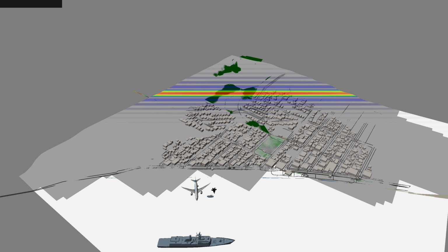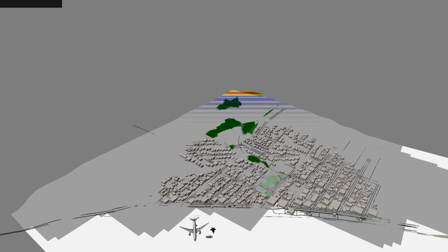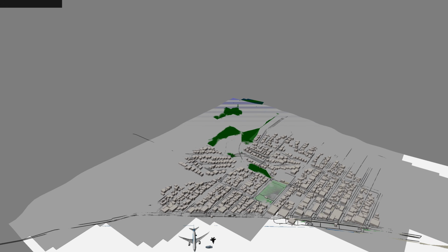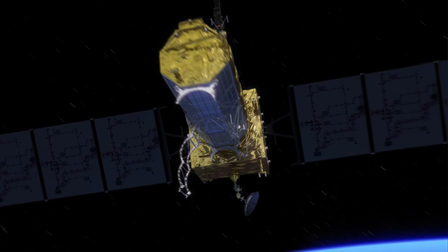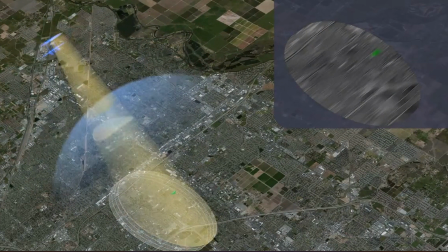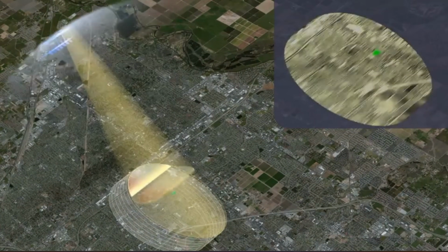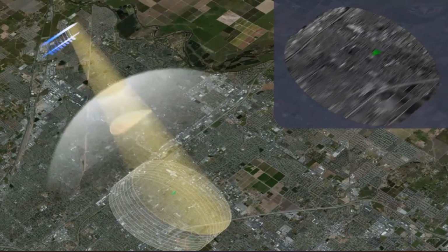It also improves the gain of the receive antenna, improving the signal-to-noise ratio. So scan on receive will improve the range ambiguity limitations, and this will allow for higher PRFs in each of the sub-apertures or channels. An early adopter of digital beamforming scan on receive technology is the NASA NISAR satellite, which was launched in July 2025. Here I show a video from NASA, and you can see in this animation how it is working.